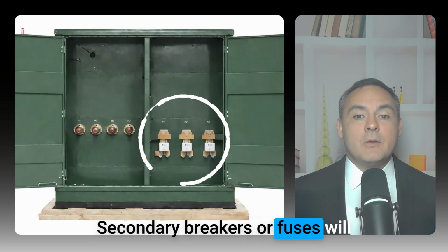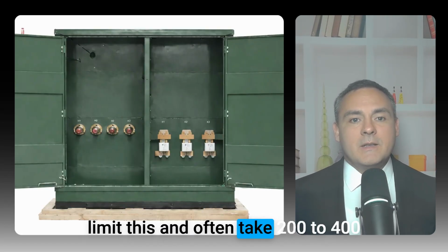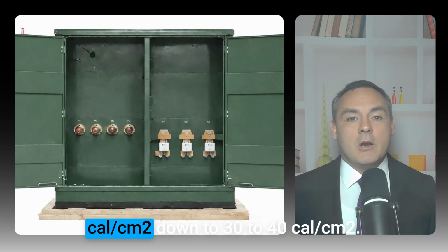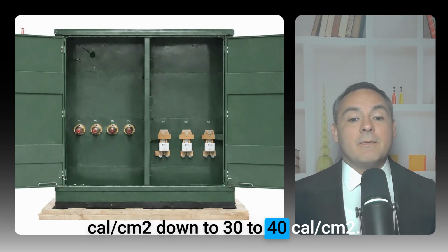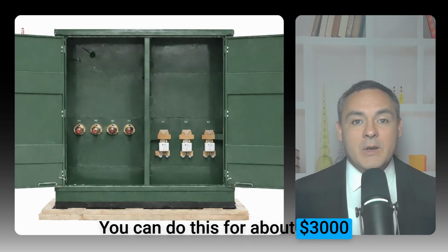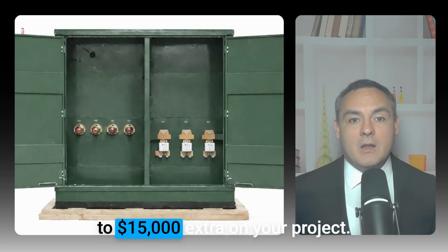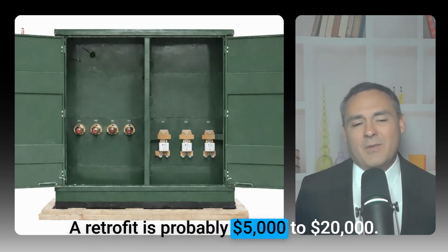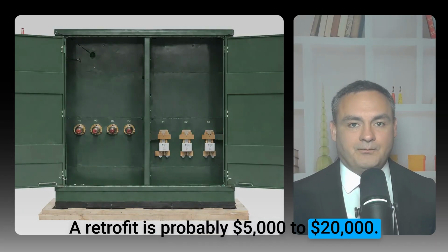Secondary breakers or fuses will limit this and often take 200 to 400 calories per centimeter squared down to 30 to 40 calories per centimeter squared. You can do this for about $3,000 to $15,000 extra on your project. A retrofit is probably $5,000 to $20,000.